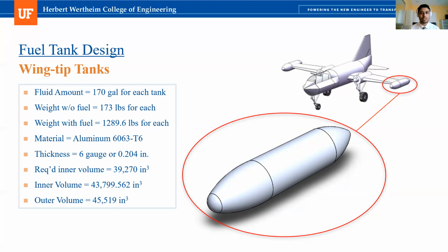And the reason why we would want to reduce that is because when it flutters, it causes fatigue in the wings due to it being subject to a lot of bending moment loads. Also the wingtip tanks provide a little bit of aerodynamic benefits, such as reducing the vortices that are usually created on the tips of the wings as a result of lift-induced drag. Next slide, please.